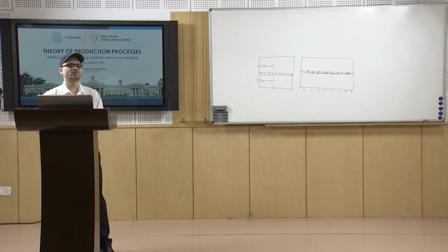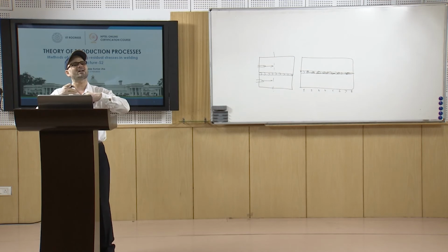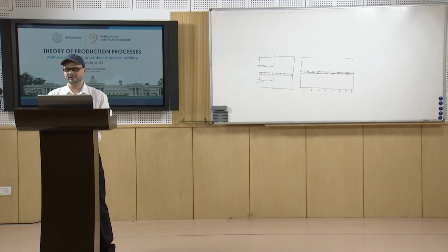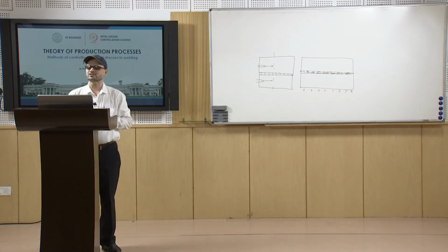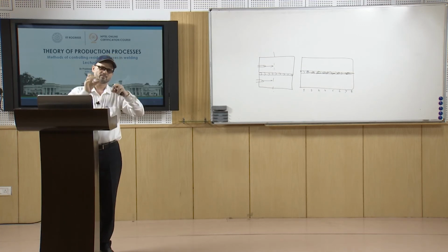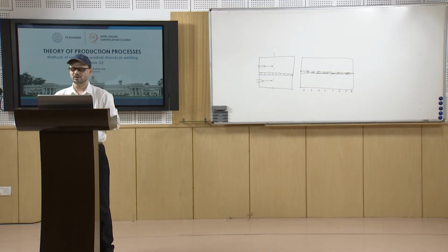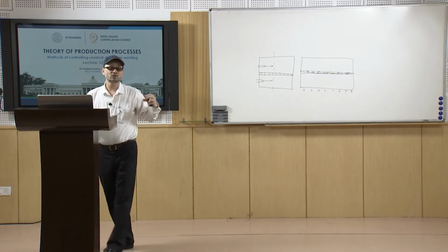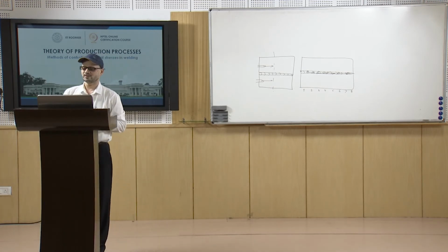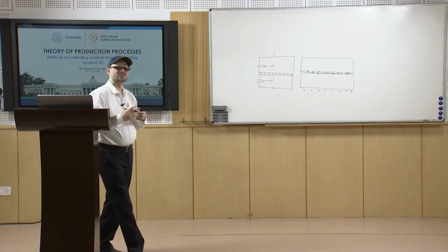In case of plate panels, when we have the transverse welds arranged in a staggered pattern, then to avoid the weld intersection, discontinuous transverse welds are first welded, and then we weld the longitudinal welds. So, first of all we will be welding the discontinuous transverse welds, and then we will go for the longitudinal welds.